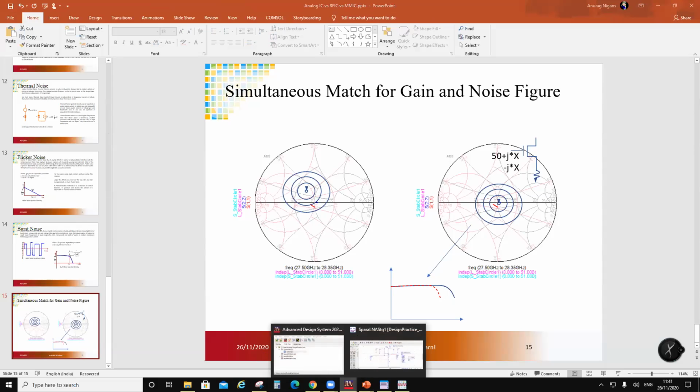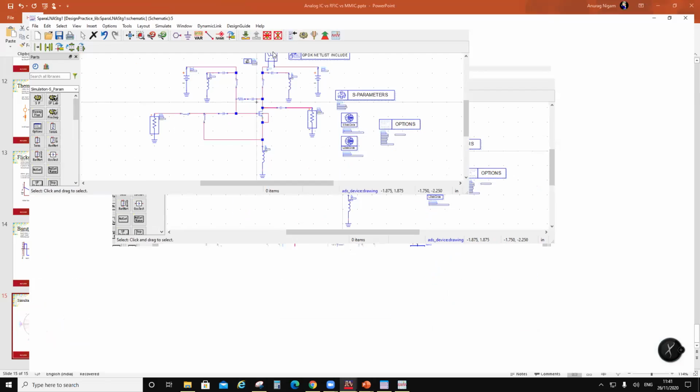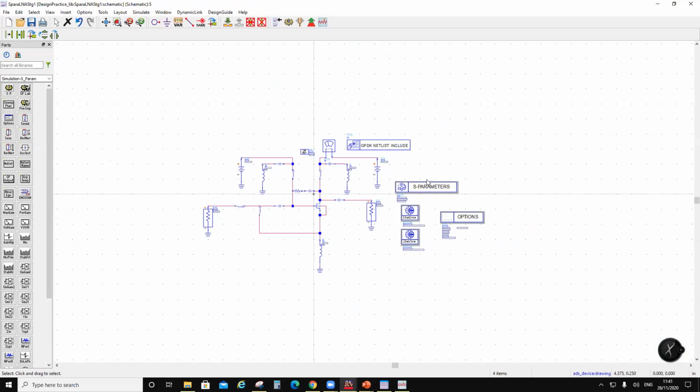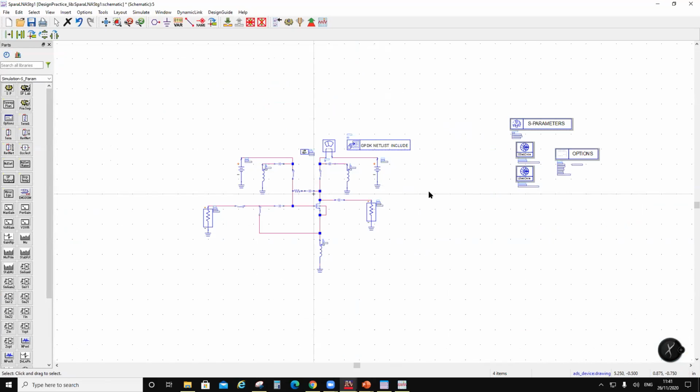Okay, so we have designed a single stage. Now let's say I want to do a 2-stage. So now this one is for your noise figure. Usually, if I want to deliver certain power, I would have another stage following it, which will be for gain. But then the idea is I will increase the transistor size over here to deliver certain power. But then this is counterintuitive. Why? If I was to use a large transistor, I'll use it on the input side, not on the second stage.